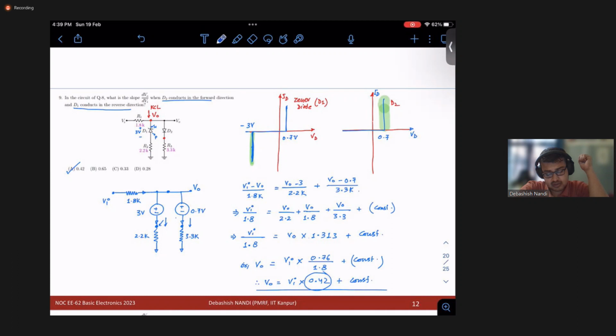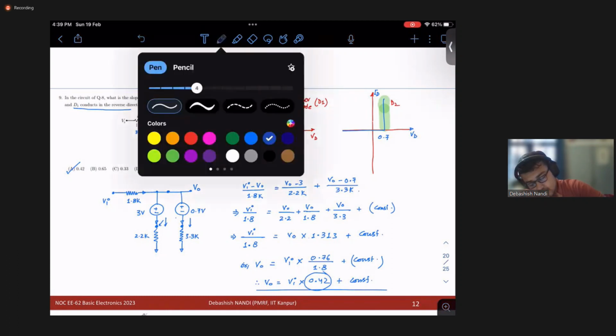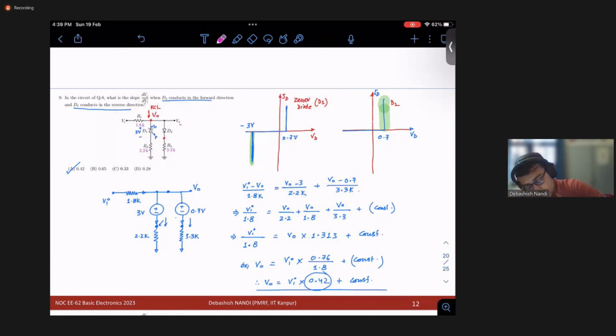Okay. So your query is how can we find out this voltage, right? Yes. And that can be easily done, right? If you know this voltage, you just subtract this voltage. And also you can see that this voltage won't change. Once the diode is on, then it is simply 0.7 volt.